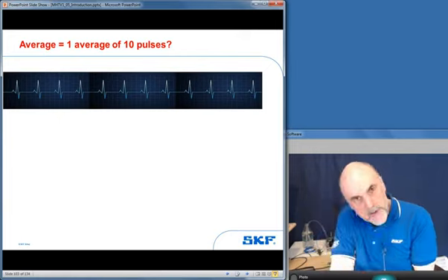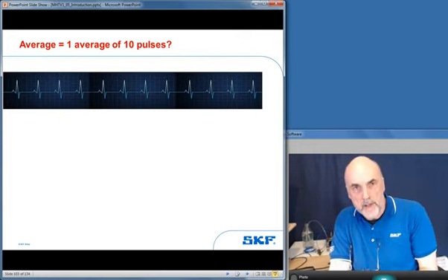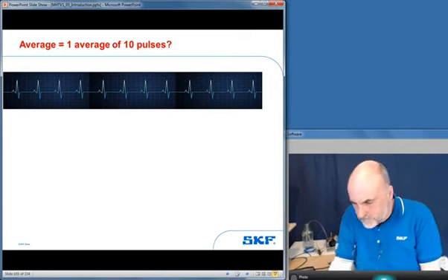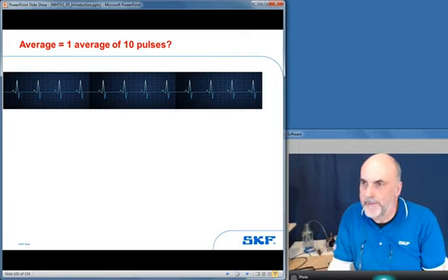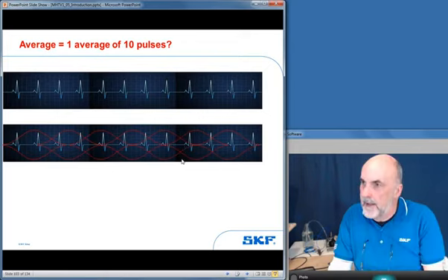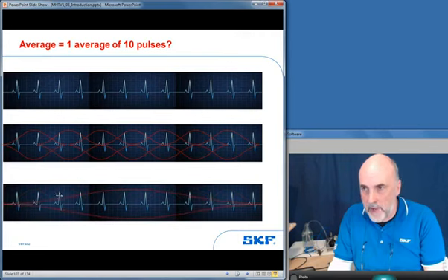So if you're taking the pulse of a bearing, you want to do a good job and take a representative set of those pulses. There are 2 ways that you can do it. There's the method where you can use overlapping, so you take a series of overlapped measurements. If you look at the horizon of the measurements, you can see that we've encompassed all of the pulses. And there's a school of thought that says you take one long measurement.